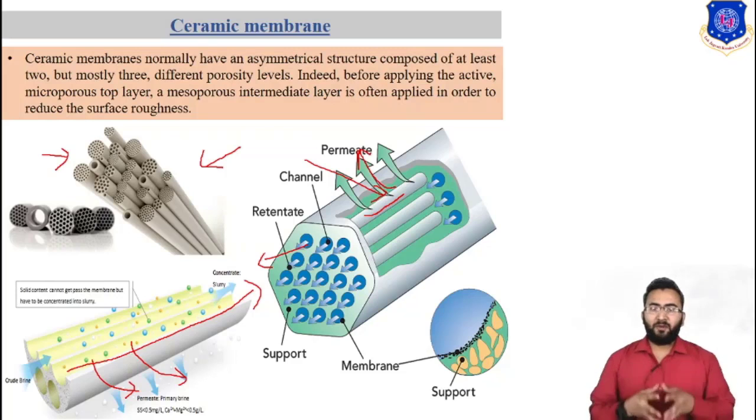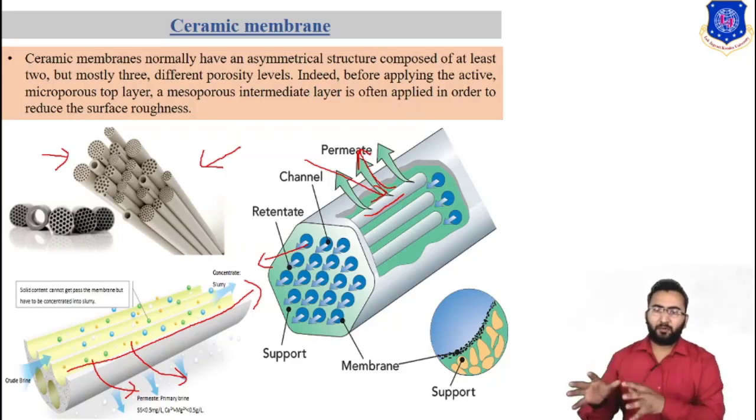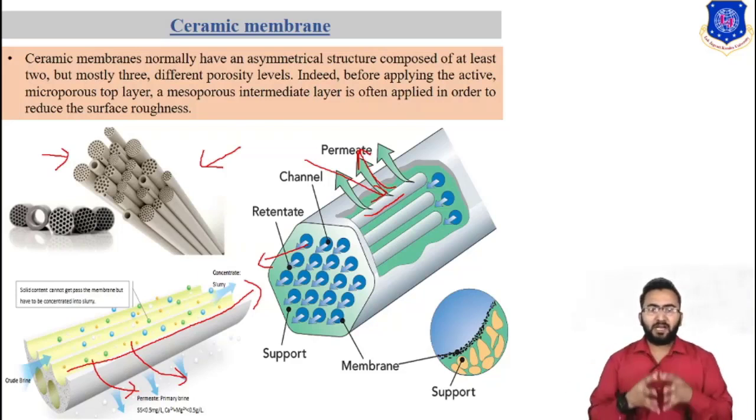Porous ceramic in the form of a thin disc has potential as a new type of membrane which limits the commercially available polymeric membrane presently being used in low volume application for sterilizing filtration or particulate filtration. However, in order to propagate this approach, it is essential to resolve certain basic aspects of the ceramic membrane, such as scope of pore size control and structure stability of the thin disc particulate due to the reduction in thickness and brittle nature of the ceramic material.